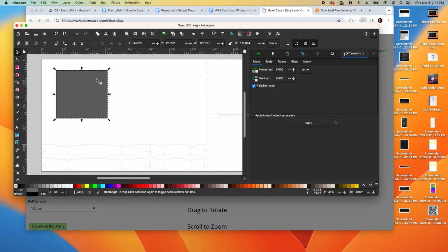I want to get rid of this stroke around it. It's got this black outline around it, and that's going to mess up my dimensions a little bit. So I'm going to right-click over here on the X and hit Set Stroke, and that gets rid of that. For anything where we're trying to be very precise about the placement or the size, you want to get rid of the stroke because it complicates the overall size. So I'm going to set the width of this to 100 and the height to 100, because this rectangle is going to represent one of our printed circuit boards that we're going to be modeling.